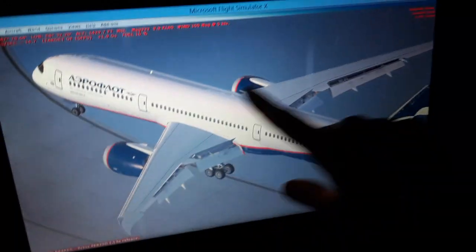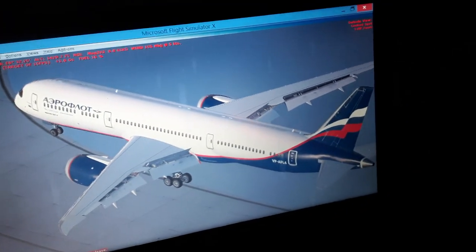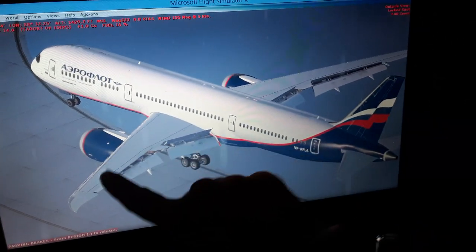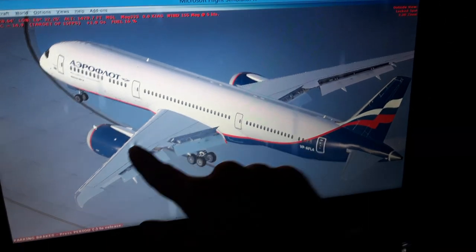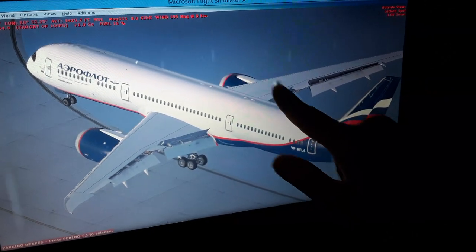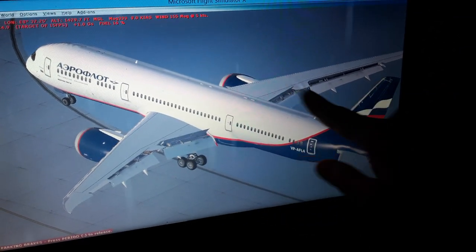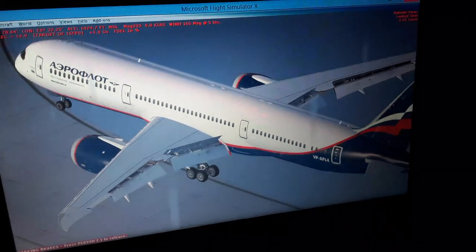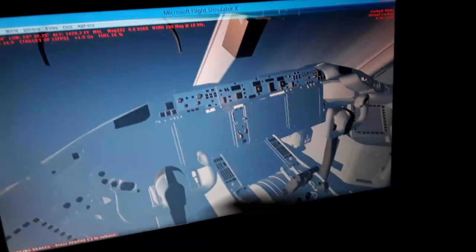You see the wings hold the weight of the aircraft, the forward wings when we fly mainly. You can see also we have the mean aerodynamic chord position, the MAC, which is where the maximum aerodynamic lift occurs in flight. It is where also the center of pressure is moving forward and aft in the top surface of the wings. Also where the stall will begin: the flow of the air from the top surface becomes detached, and we have the aircraft stalling the wings for a given angle of attack.